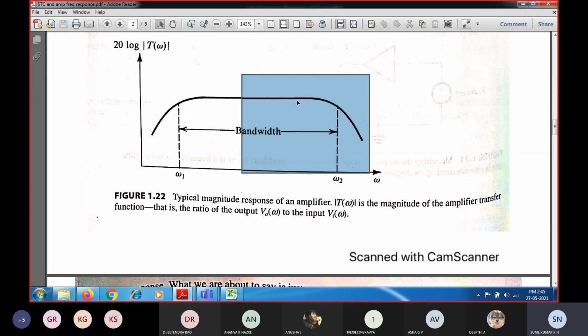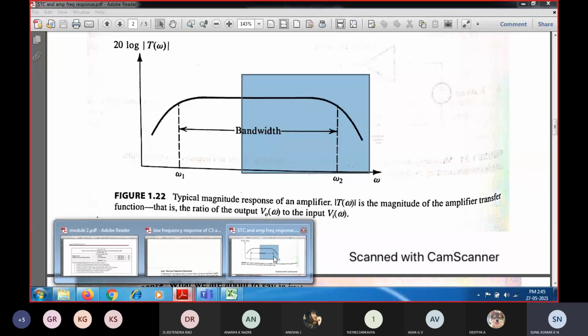model, we can see the amplifier gain will be constant and it will be maximum during the mid band frequency range. And as you increase the signal frequency, you can see the gain getting rolled off. That means the gain gets reduced in the higher frequency range. That is because of the internal MOSFET capacitance. So since we are discussing all those things, we can say that in the high frequency response, at the higher frequency range of operation, you can see a sufficient amount of gain getting reduced as you increase the frequency to a higher level. Okay, so this causes the gain to get reduced at higher frequency.